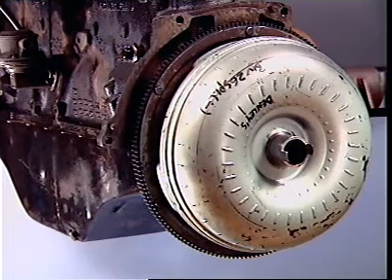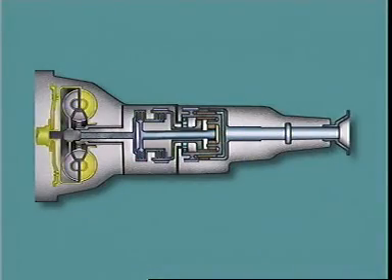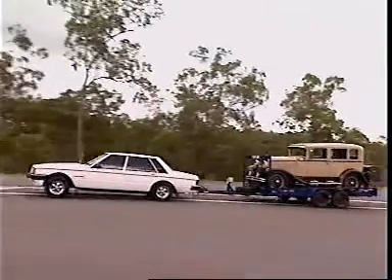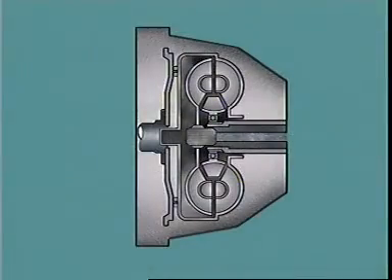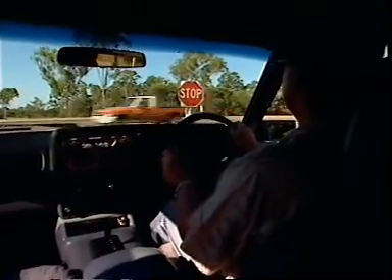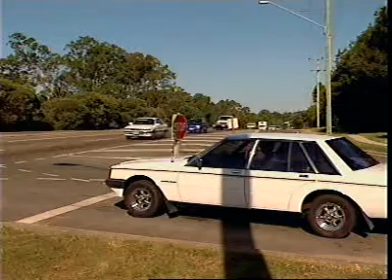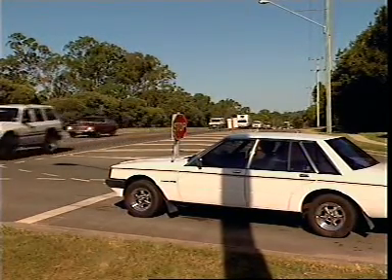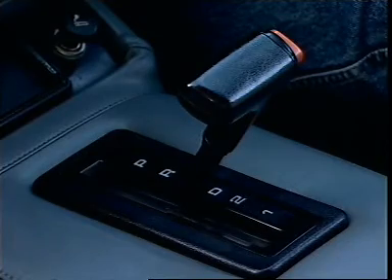The torque converter is mounted on the engine in the same place as a manual clutch and does the same job, transmitting engine torque to the input shaft of the transmission. It can also multiply torque according to driving conditions. It's a fluid coupling, with the fluid acting as the driving medium, since none of the converter components are physically connected to the others. It acts as an automatic clutch. At engine idle speeds, it allows the engine to operate while the vehicle is stationary and the transmission is in a drive range.